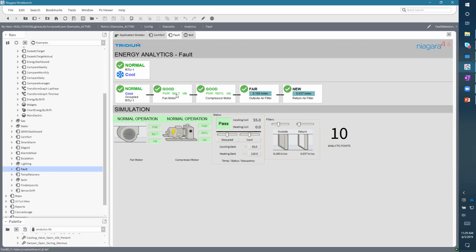If I have a belt that breaks on a rooftop unit, I could then indicate that there's a failure. So here I show it in this little line. You'll see here that I can show it on a grid to say, hey, this is kind of like a bingo board that said the power's failed, the belt broke. If I have some vibrations, I can show that up in maintenance. Necessarily, not necessarily a problem, but I want to have somebody check it. The refrigerant's low, or we lose power on the compressor, lose power on the